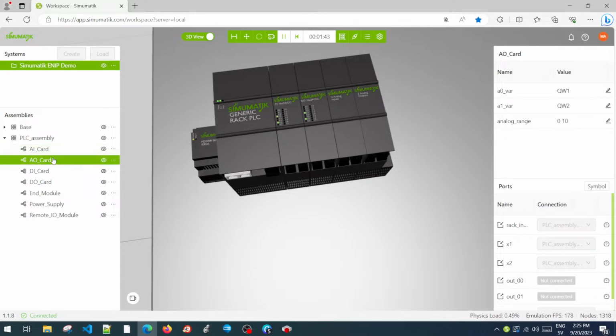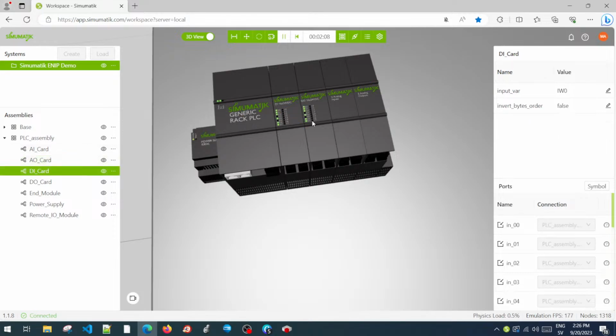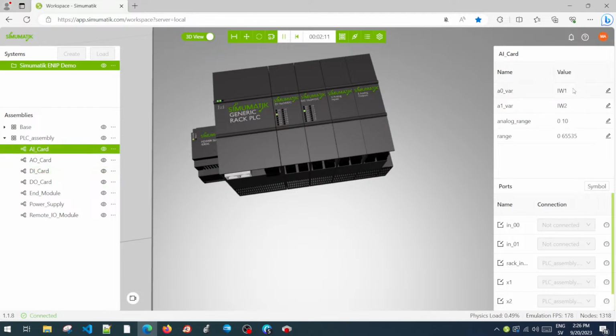Yeah. But this is if we remember that we say that we will exchange 10 bytes back and forth. What we are saying is in which position we are sending this input, digital inputs and outputs, okay? In which position on these 10 bytes. So basically what we are saying is that the digital inputs are coming in the first 2 bytes and then the analog inputs in the second and the third and so on. So this is, let's say, in the telegram we are sending back and forth. How are we sending it?